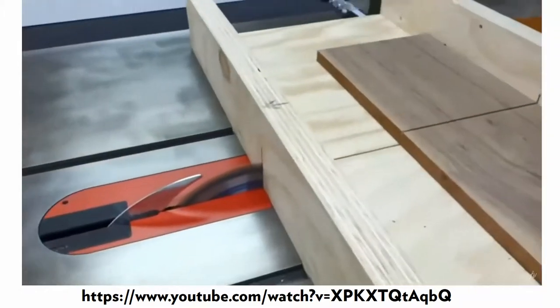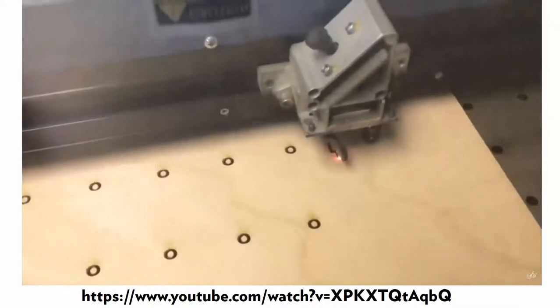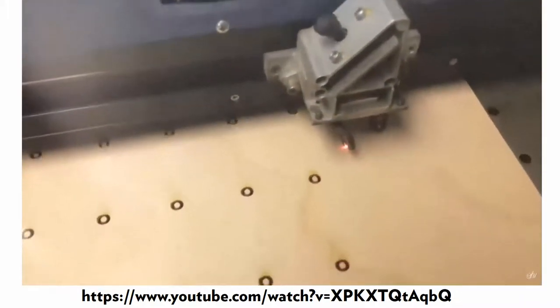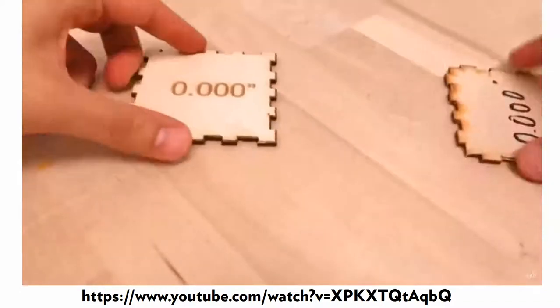You're going to see on a table saw, it's going to be really easy to see. And lasers have a kerf too, it's just really, really small. If you don't account for kerf, your tolerances are going to be off and parts aren't going to fit. So I created a test with 3 finger joints and 3 different kerfs.